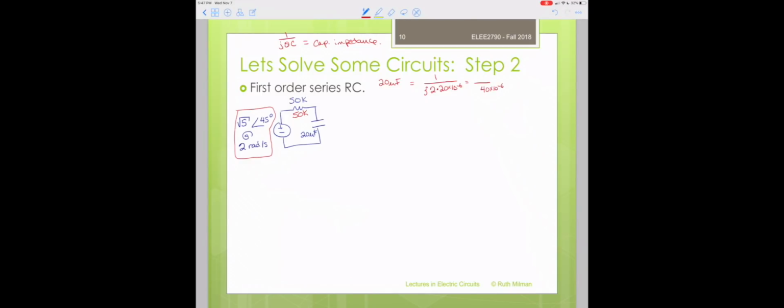Move that up to the top, rearrange slightly, and before I say that, we're going to multiply by j/j. As we multiply that, we're going to end up with j times 25K. So remember that on the bottom, j squared becomes -1, so this value is actually negative. Our impedance here is minus j times 25K. So if we're going to draw this as an equivalent circuit, then we're going to place one impedance in it, and that one impedance is going to be 50K minus j 25K.